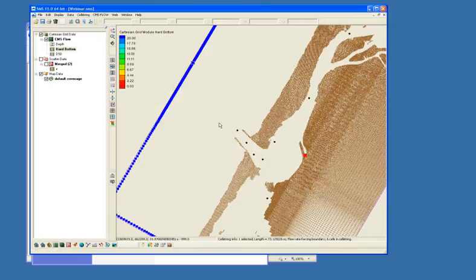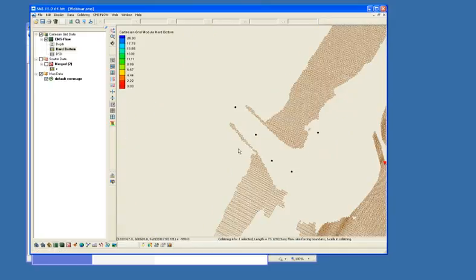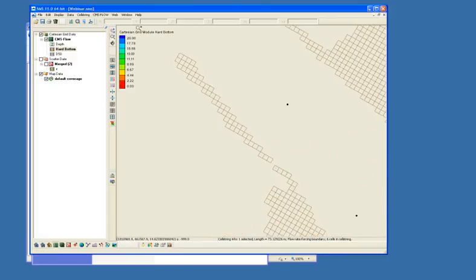One thing that you can do, and that we do sometimes, is I'll just zoom into a certain area here. To set those values, you would select a cell, and so I'm just going to select some cells around this jetty, for example, to represent maybe the toe of that jetty so that it does not erode.